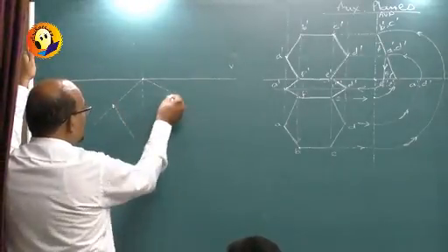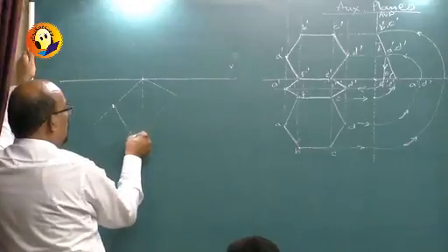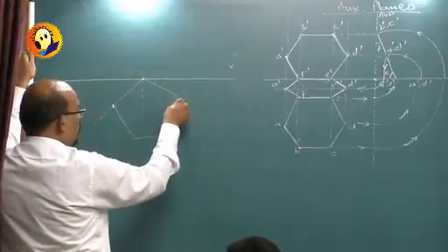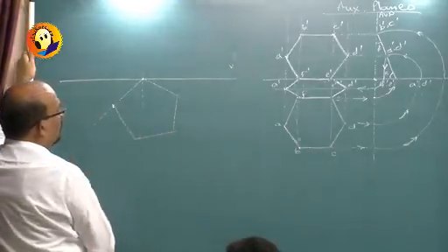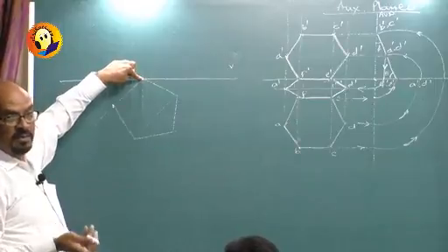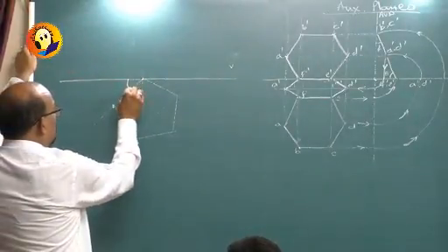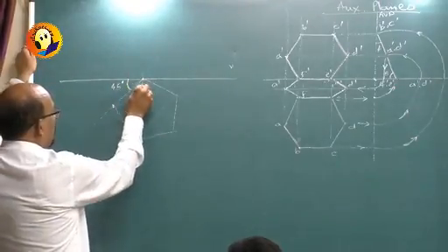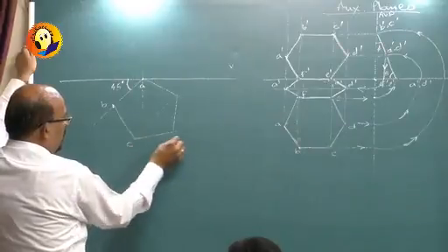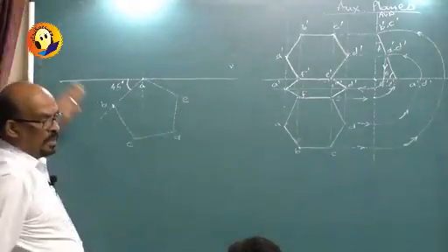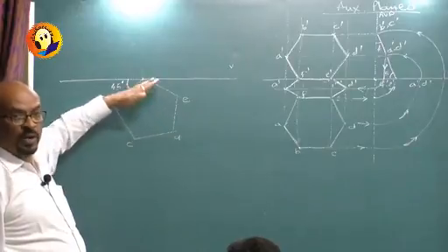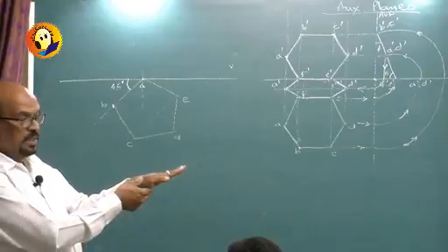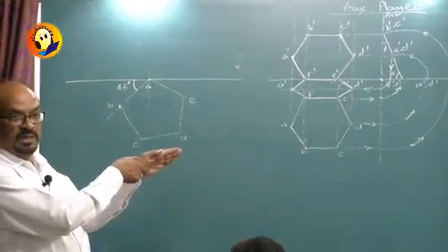So again this is the case where the line of rotation is not going to be perpendicular to XY, but somewhere else. And this point is in VP. That is, everything is fixed. We can't move from here. So I keep this point as A, B, C, D and E. Now keeping the lamina in this manner, if I am to rotate it, then rotation cannot be seen in the front view because it is not a line view. It will be something else that we can see.